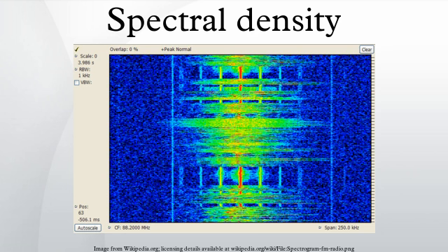Power spectral density. The above definition of energy spectral density is most suitable for transients, that is, pulse-like signals, for which the Fourier transforms of the signals exist. For continued signals that describe, for example, stationary physical processes, it makes more sense to define a power spectral density, which describes how the power of a signal or time series is distributed over the different frequencies, as in the simple example given previously. Here, power can be the actual physical power, or more often, for convenience with abstract signals, can be defined as the squared value of the signal.